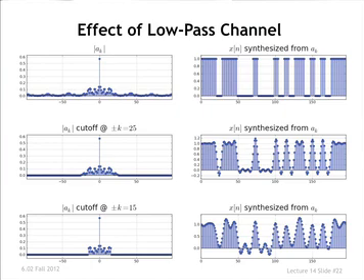Well, the higher frequency components of the signal have been zeroed out. You expect the signal to be more rounded because it can't make these sharp transitions. It takes high frequency content to make sharp transitions. So as you trim the spectral content by sending it through a channel that's not wide enough to contain all of the signal, you get a more rounded signal at the other end. You sent this, and this is what you're receiving. This is the distortion that the channel has imposed on your signal. And you can imagine if you tried to find a place to sample this, you might run into some trouble.